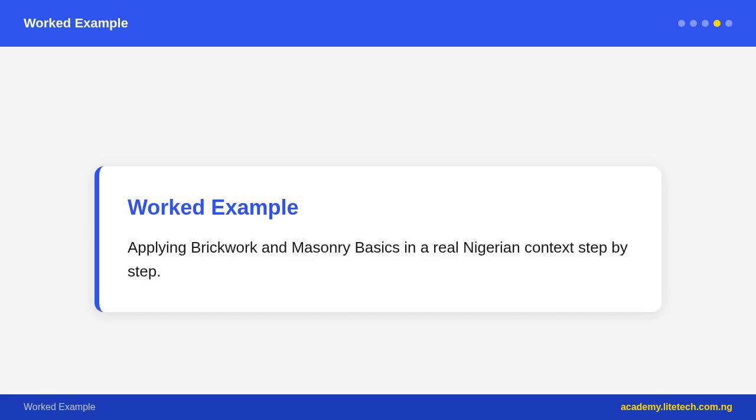In Nigerian building construction, the stretcher bond with sandcrete blocks is almost universally used for the main walls of houses. A skilled bricklayer ensures that all blocks are level using a spirit level and string line, and that all vertical joints have mortar fully filling them.